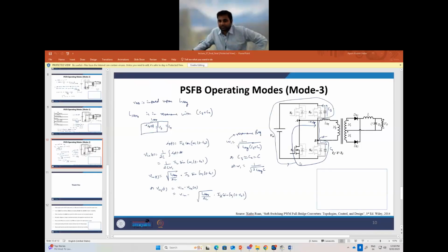Okay. So can we say here that VC3 and VC4 won't be equal, even though they are in parallel? No, during the initial period it will not settle, because there is a transient period, but it will slowly settle down to what it has to satisfy, KVL. It is only because they are storage devices, not just the passives which we have. Okay, sir. So we can say that for the transient period, KVL won't be satisfied.